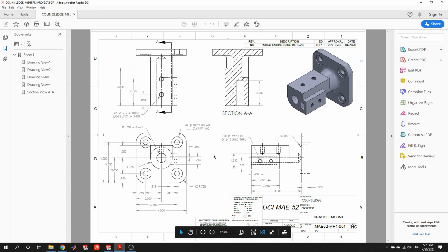So in terms of clarity, like I said, there's a lot of subjectivity in how you create the drawing, but you want to be careful. Like I said, you don't want things to cross too many lines. You don't want to have dimensions on the inside of parts. And so for that reason, you're going to have to be a little bit creative in how you stack some of these up, specifically in the area with this pocket. So there's a lot of information here, and sometimes it can be a little unclear what exactly the dimension is showing. So you can deal with this how you want. If you feel that this dimension is better on this side, just make that judgment call. But the most important thing is having all the dimensions and that they're clearly represented.